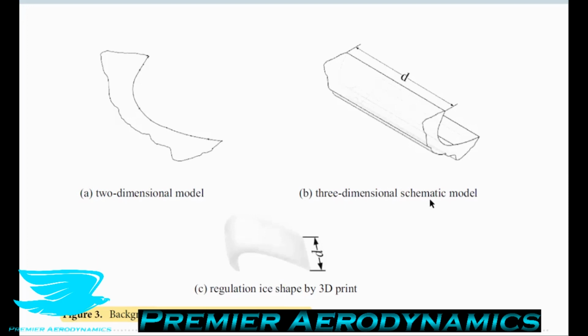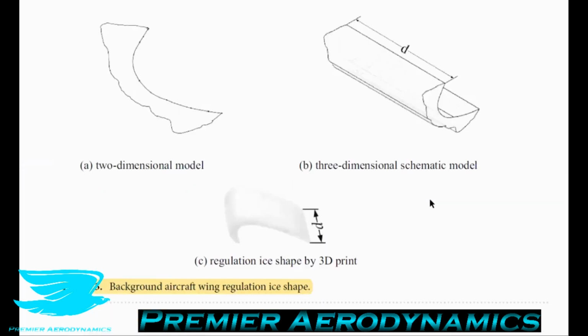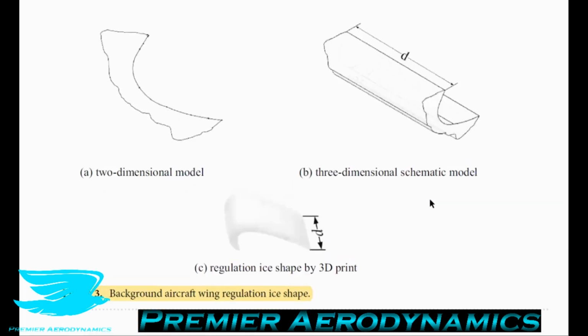Figure 3 shows the general cross-section shape of a wing leading edge with ice accretion on it. So you have the cutout of the leading edge, and the ice is just being built up on the front, and it really doesn't have much of a rhyme or reason in terms of its geometry. It's just quite random, jaggedy and rough. So that's not going to be good for an aircraft, you can see immediately, unless you have a very small aircraft where perhaps turbulating the flow would be beneficial. But for passenger airplanes at least, this is usually not good.